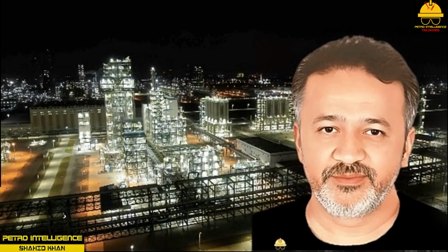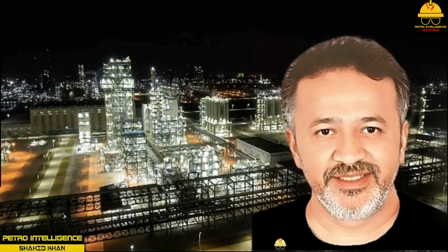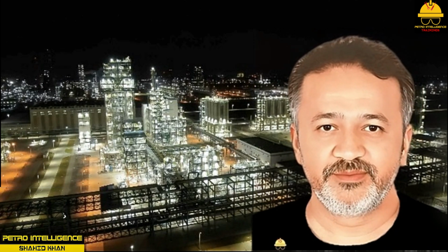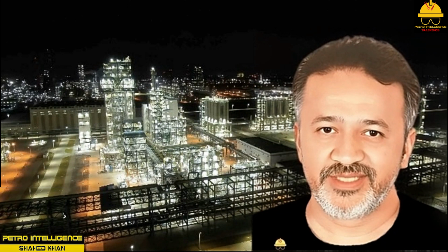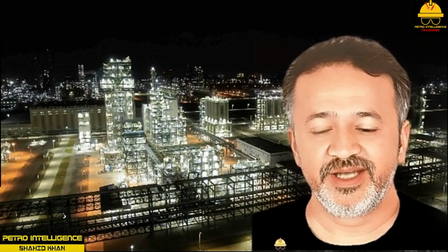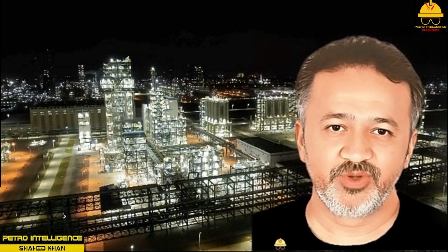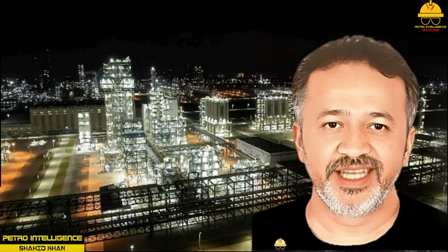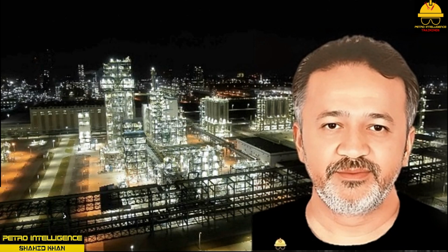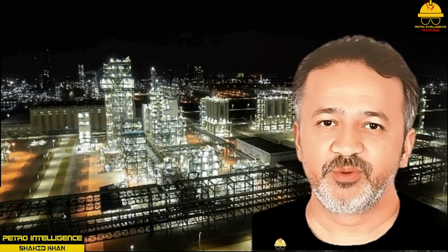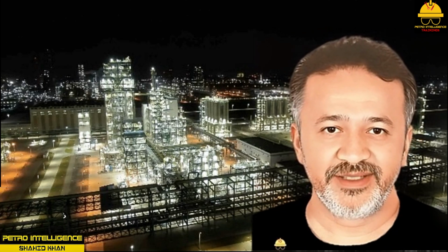Pressure symbols. The most common pressure devices are pressure gauges, manometers, and pressure transmitters. Pressure gauges are represented on a P&ID as PI, or pressure indicator. A circle with PE is the symbol for a pressure element. A diaphragm in a DP cell is an example of a PE. A simple equation can be used to determine pressure, P: pressure equals F, force, divided by A, area.